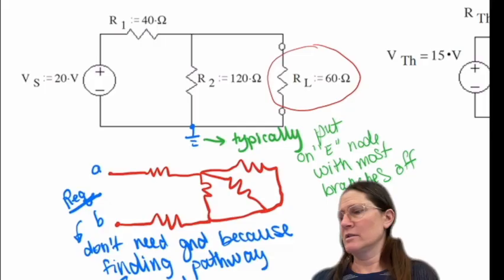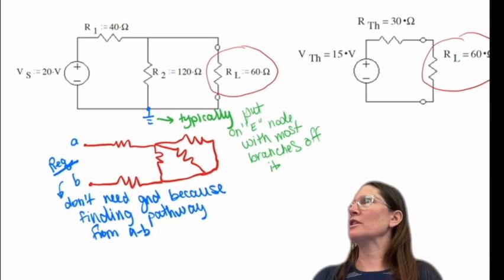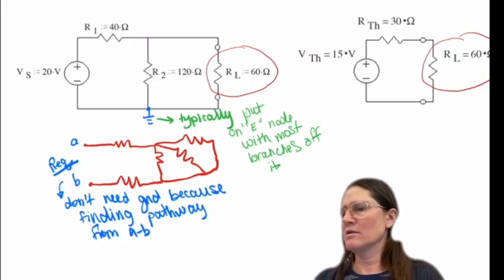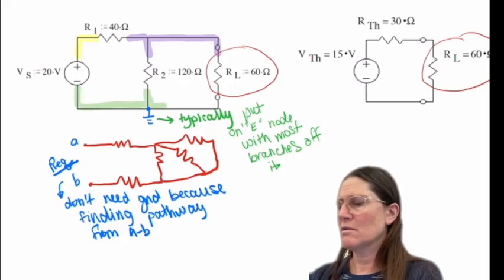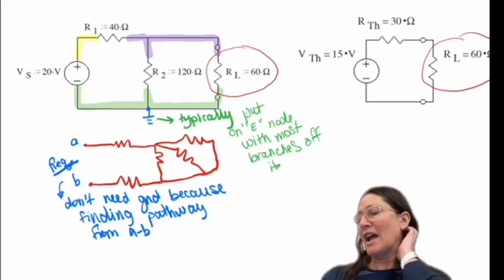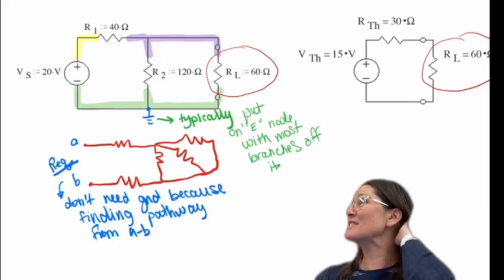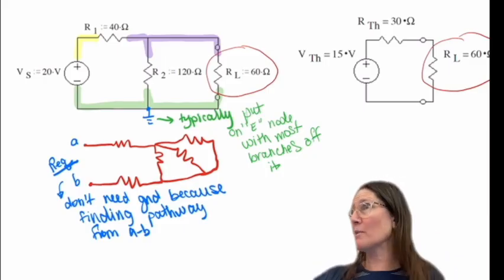Yes? Was there another question? Yes. I was wondering if there's an essential node on the top that's next to the positive side of the battery or the source, and that happened to be the one with the most branches. Would you suggest we put the ground on that, even though it's on the positive side of the circuit? Again, that goes into preference. I again like the bottom, so I'd probably put it on the bottom still, because visually that looks better to me. It is going to add another unknown at the top if there were 4 branches off that instead.